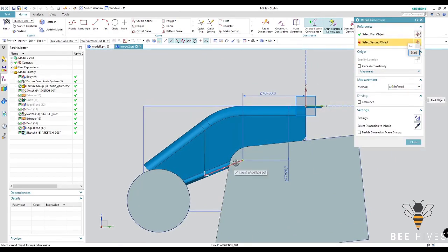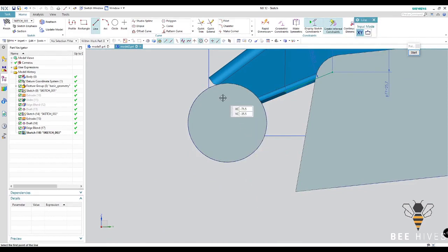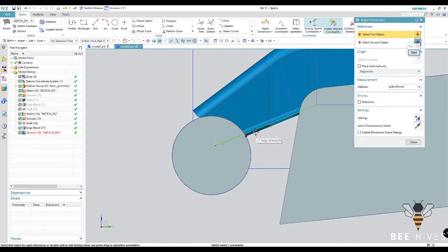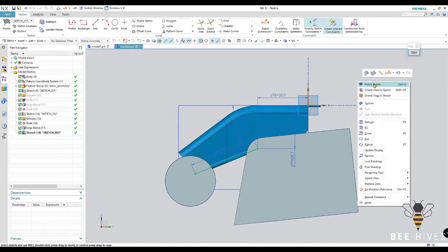I'm gonna give now angle. This seems to be 22 degrees because it was already matching. So I'm gonna go with the line again and extend it to that point. Simply trim off or delete or give a dimension to the length. Let's say 40. That's it. So we have a line fully constrained. Just finish it.